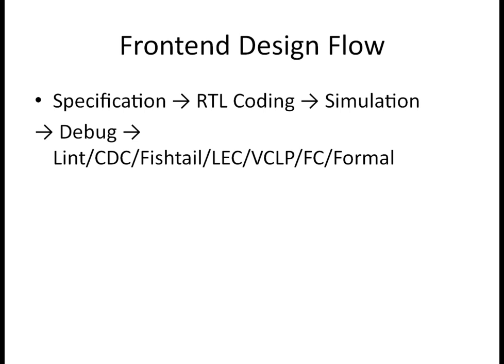Next are combinational loops and multi-driven nets, bit width mismatch, overflow, underflow, and we should not use blocking statements in sequential blocks, and non-blocking statements in combinational blocks. So these are the rules which we are going to check in lint.